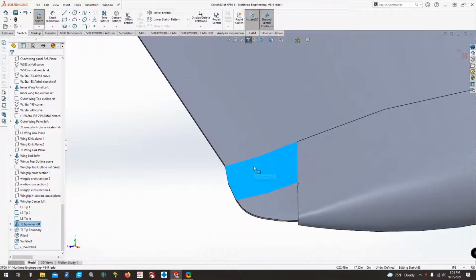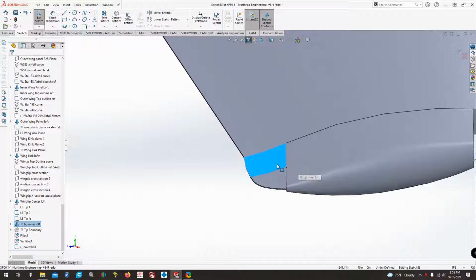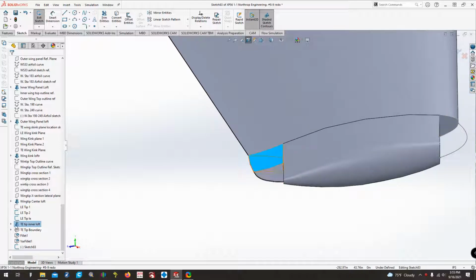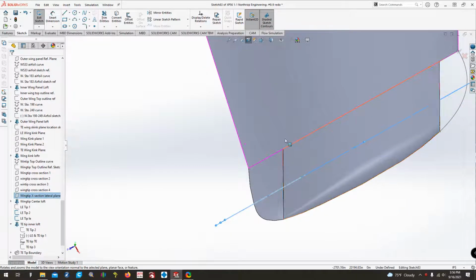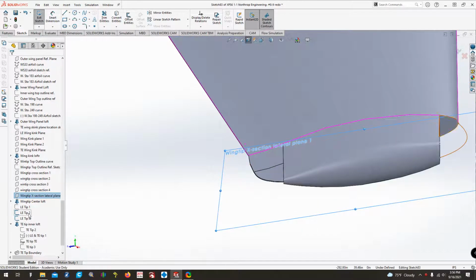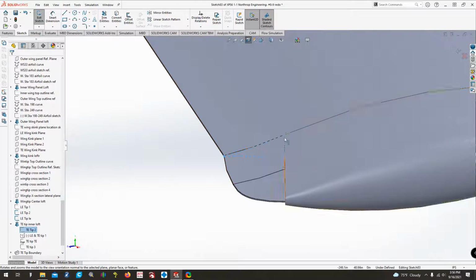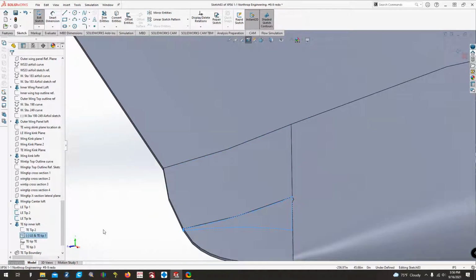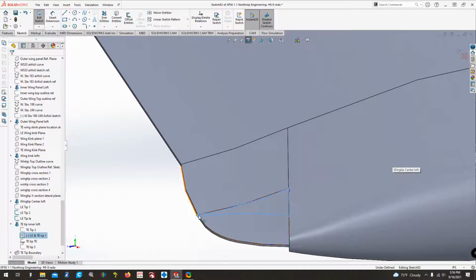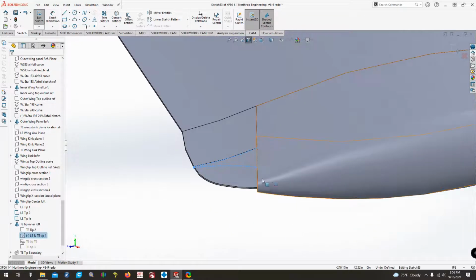This one right here, basically what I did is I created another cross section, and I put in another plane that's parallel with the end of the wing. Then I did a cross section of this original part we lofted, sketched on that face to create the blue sketch you see in there, and used the intersection curve tool to come up with this little airfoil section here. I could have done another plane further out and continued this on, which I may still do.